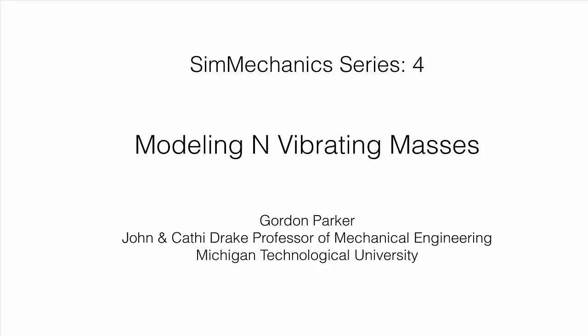But in all of these videos, we were focused on a rather simple single mass system, and thus we weren't exercising what I would argue is a significant feature of component-based modeling code such as SimMechanics. In short, we can change in seconds the complexity of a model and explore the effects of the change. In our case, this means going from one mass and spring to having 2, 3, or 4 or more.